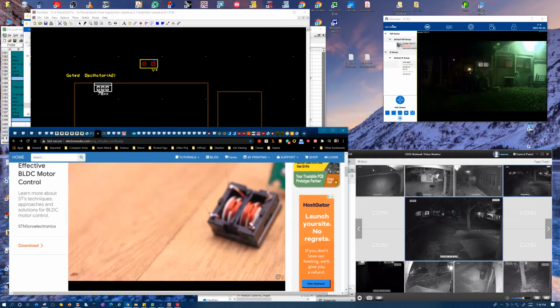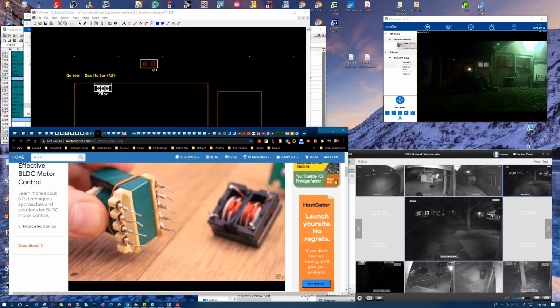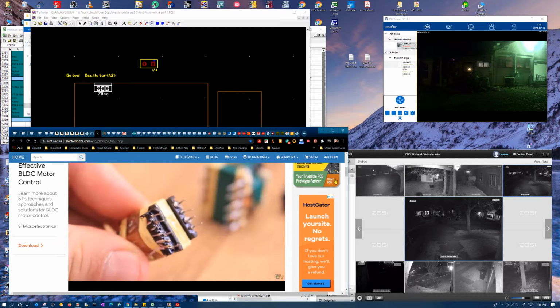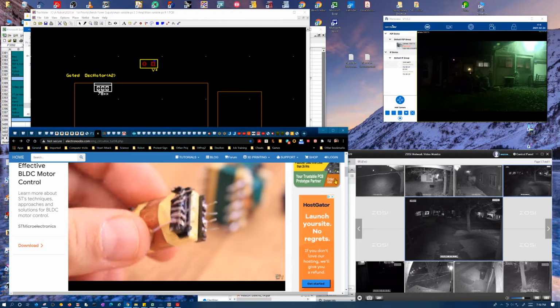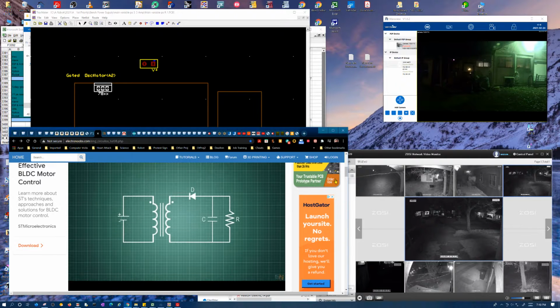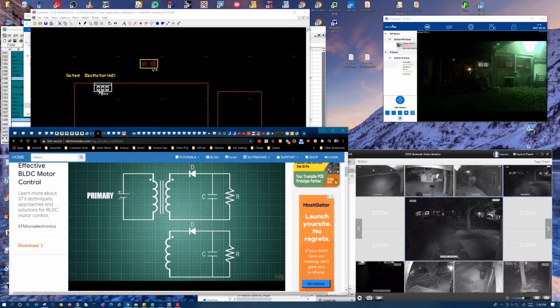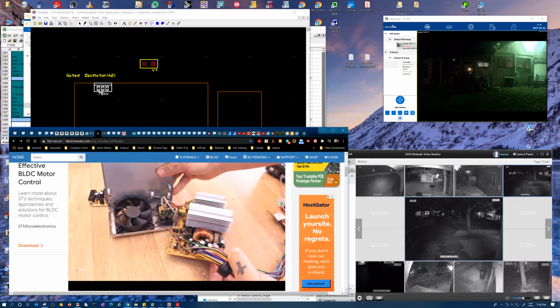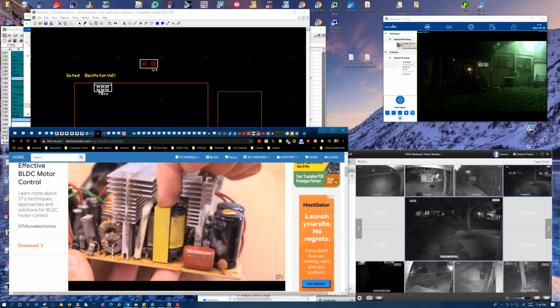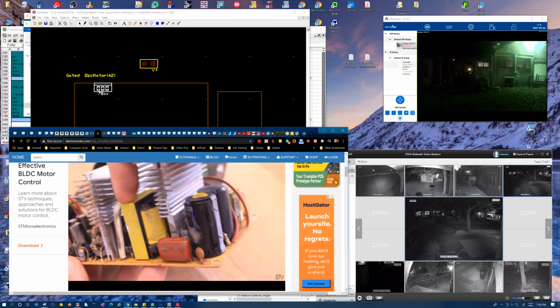Another advantage is the use of multiple outputs. Remember at the beginning that we saw that one transformer had a lot of outputs, and that's because to the same primary inductor, we could add multiple secondary coils with a different winding ratio. In case of 2 outputs, the energy that builds in the primary will then divide for 2 outputs, and we could have different values at the output. We could even have one positive and one negative output, depending on the configuration. That's why switch power supplies with multiple outputs like this one here will have a big transformer with multiple windings.